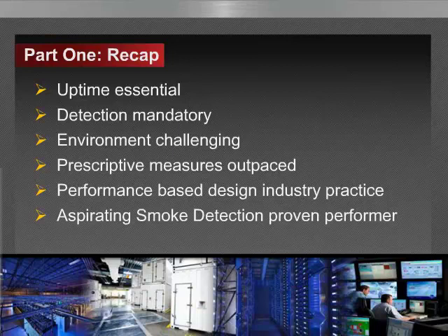So automatic fire detection systems play an essential role in the overall fire protection strategy, providing a first line of defense against fire, that being thermal, or smoke being non-thermal threats, and early intervention by personnel to mitigate potential incidents. It potentially mitigates the need for fire department response, and initiates sequential systems or procedures such as fan shutdown, suppression release, transfer of data, and so forth.